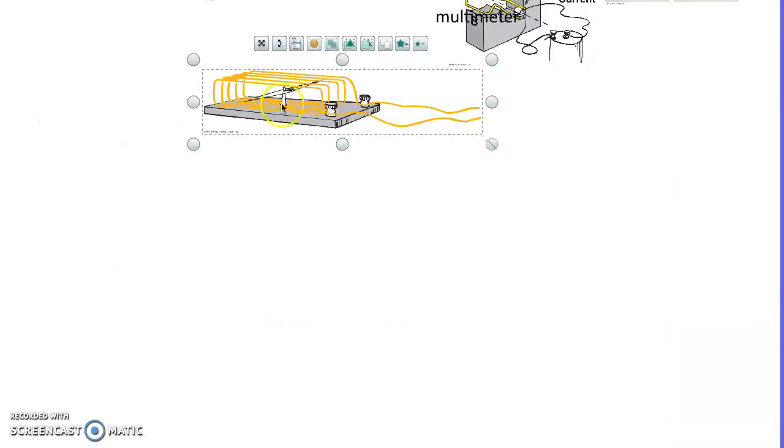Deflection is one reason you have to be careful using a compass. If you're near any electrical wires that might have a fairly high current, they may have a magnetic field. Also, any large metal objects that might have domains of their own can be enough to cause error in your measurements. Otherwise, you'll end up going the wrong direction.